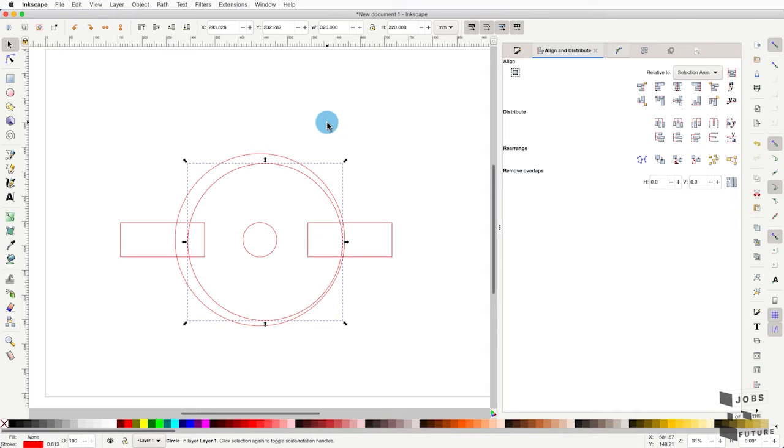You see now that I wrote this dimension twice, but what happens if I click on this locker here? If this icon is locked, I can change just one dimension, for example 310, and you see that also the other dimension changed. So it means that the aspect ratio of the shape is always preserved.